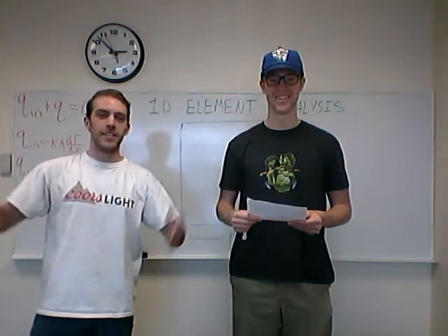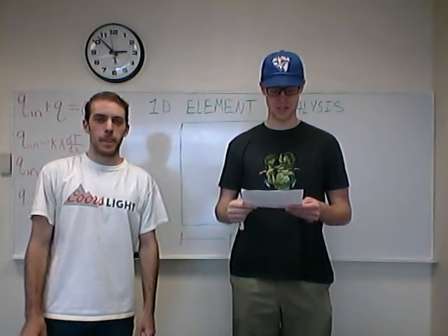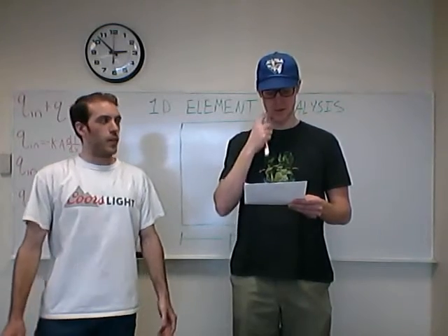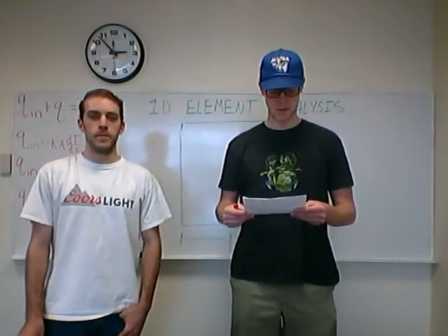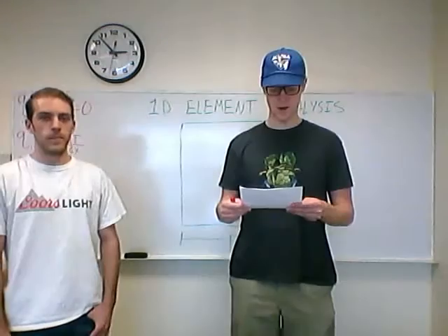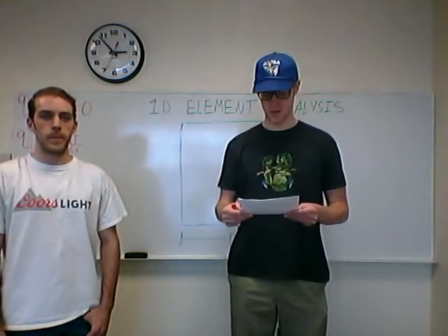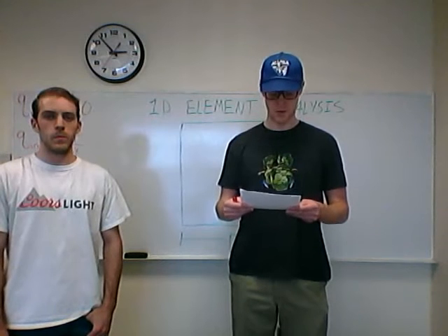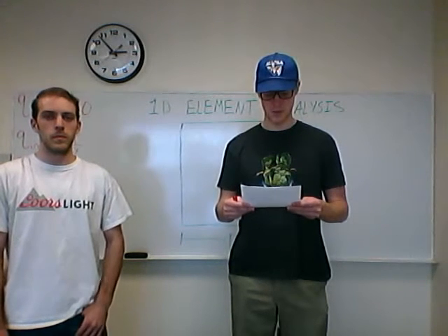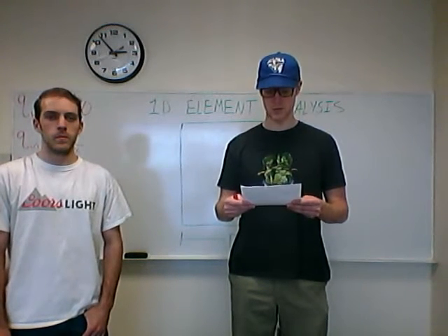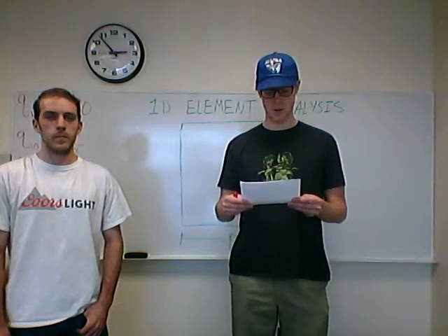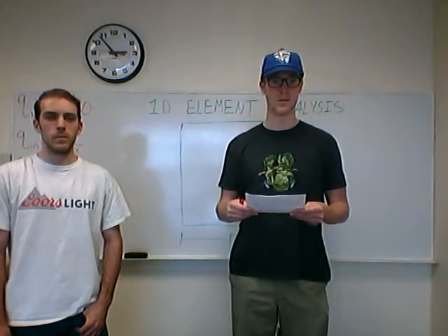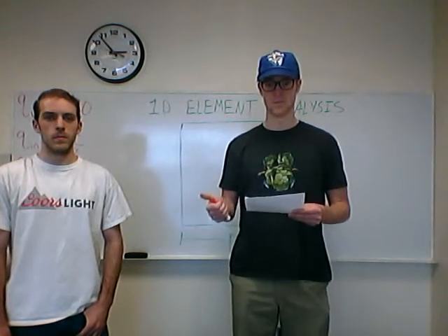Hey, I'm back. Now I'm going to be discussing how to define elements. The solid being studied is divided into rectangular elements, each element containing a central node. The dimensions of each element are created based on the number of nodes needed or wanted for analysis of the solid. More nodes mean smaller elements and greater accuracy of the solid being studied.